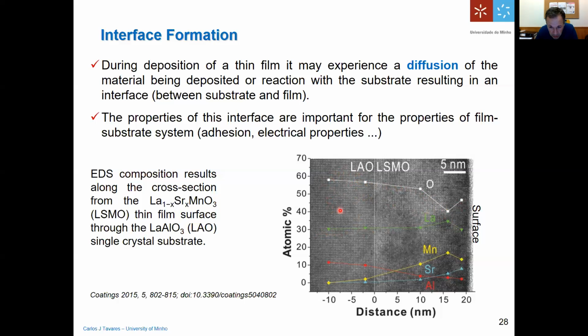If you just look at the dots, it looks like you have an epitaxial structure, and it is, but due to these stacking faults and due to this diffusion, and you have to take into account that the films were grown at a temperature higher than 500 degrees C, and the higher the temperature of the growth, the higher the energy that these atoms will have.